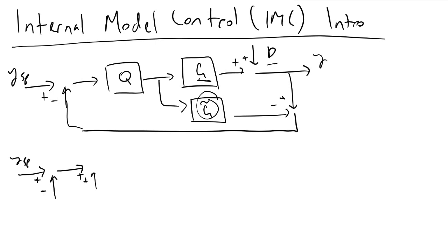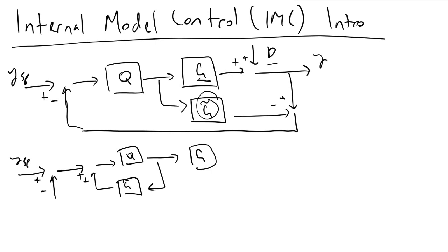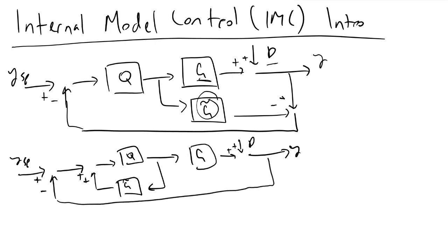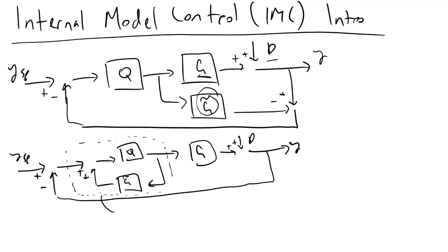And we will have, if we implement a control block diagram and modify the above diagram, what we would see is that we can rewrite this as g tilde, our internal model, and our internal model controller function q. And this is what's actually going into our process G. And so rewriting it like this, including our disturbance and our output, as well as the feedback, we can now recognize that we can define this inner loop here as an additional transfer function, which we refer to as GC.